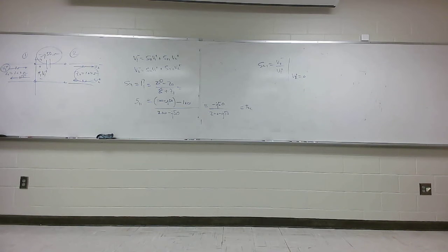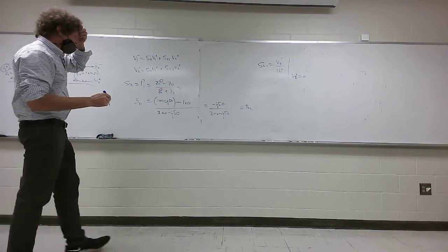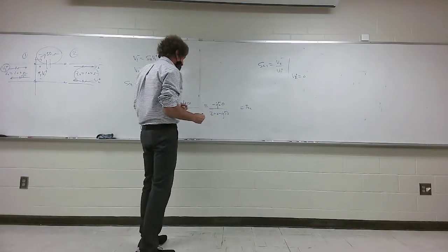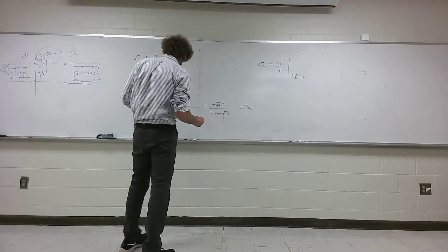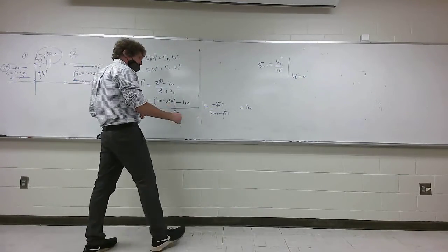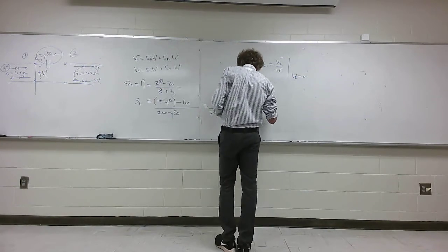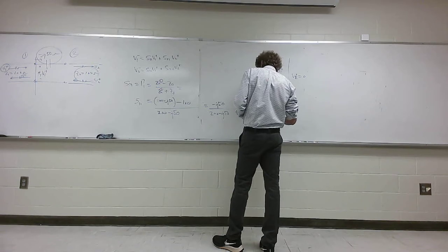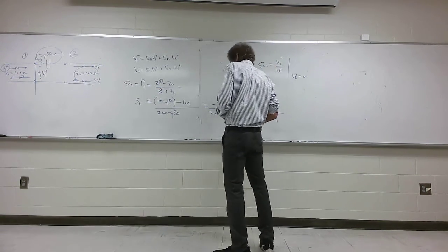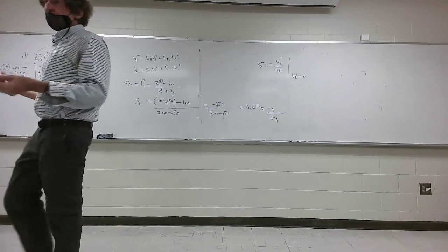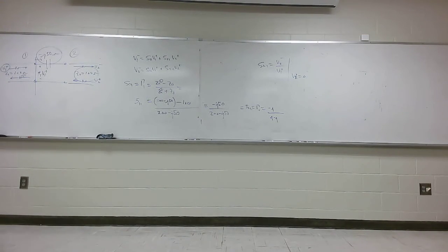Y'all with me? All right. Well, how do we get the transmission coefficient? If this is the reflection coefficient on port 1, which would be minus j over 4 minus j, I'm going to just leave it as that. What would I do to get transmission, guys? Just add 1 to it, correct?